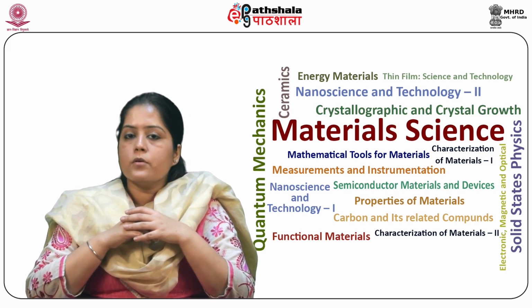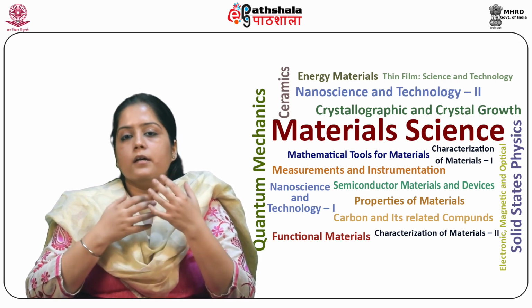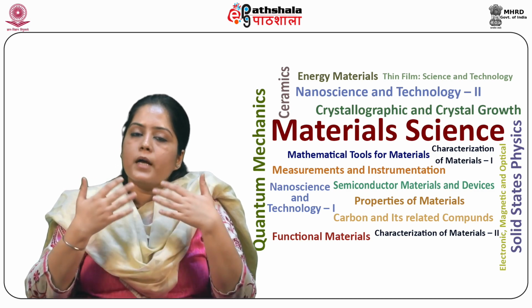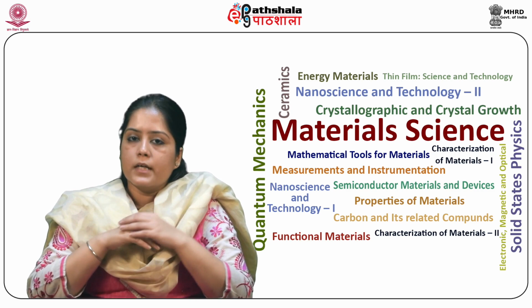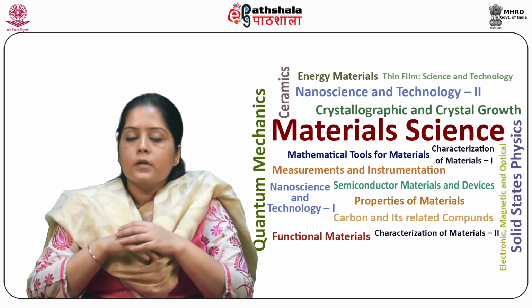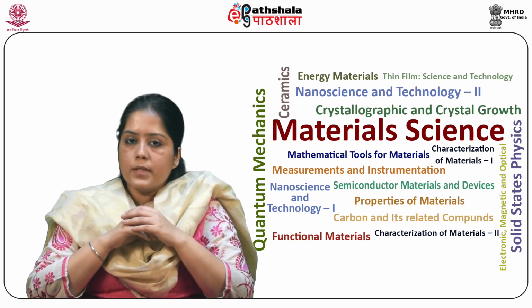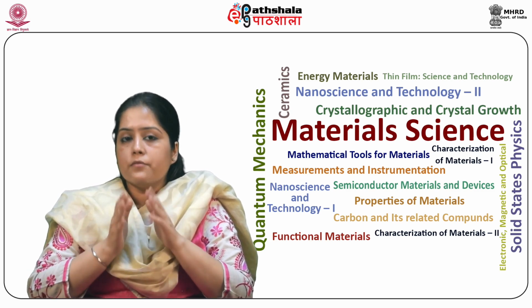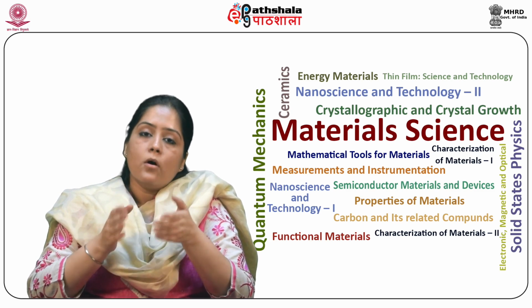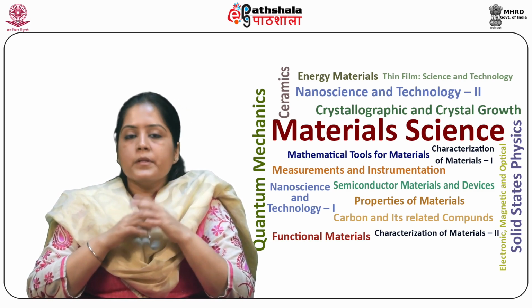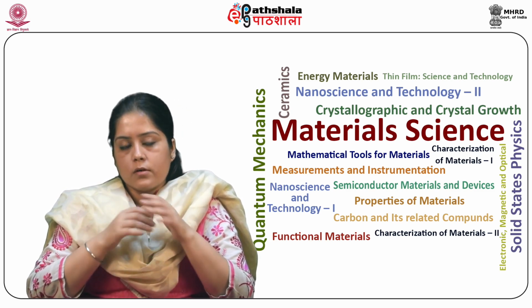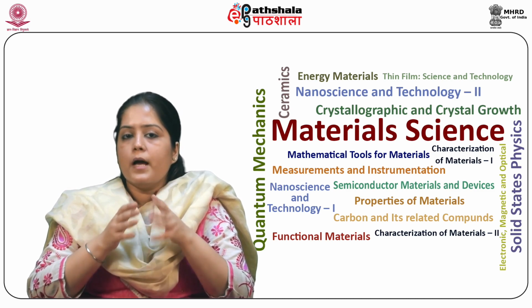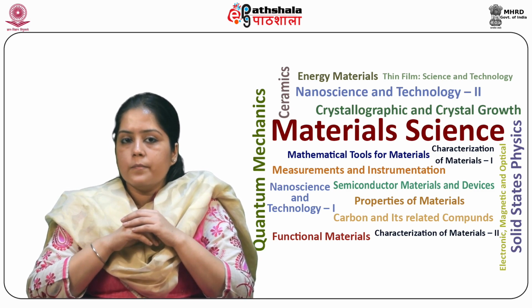High absorption coefficient greater than 10^5 cm inverse with a direct band gap of 1.5 electron volt. Junction formation ability. It should have high quantum efficiency, long diffusion length, low recombination velocity.